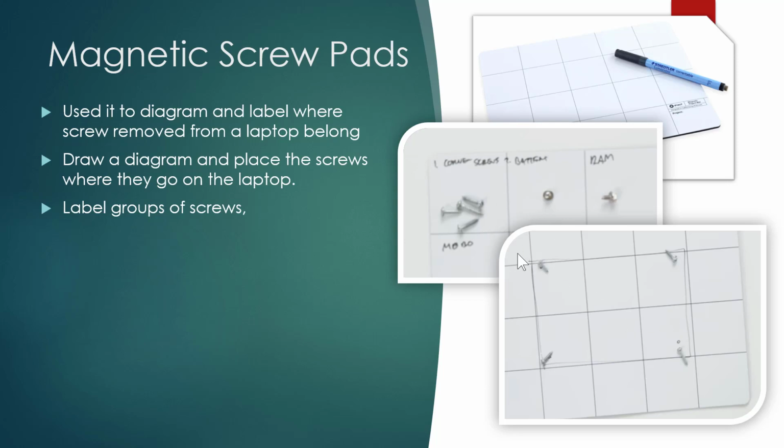Now, these two pictures right here, they're showing you screws that are not from laptops. They're usually much smaller. But one of the things I really like to do, if I start taking a bunch of screws, like to take a back cover off that's got a bunch of screws, I will draw the back cover, and where I took the screws out, I'll put little X's, and I will put the screws on top of the X's.